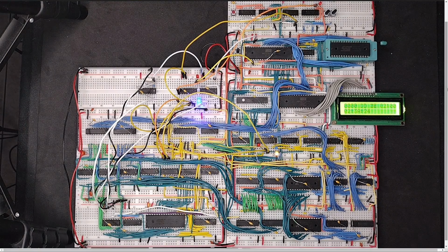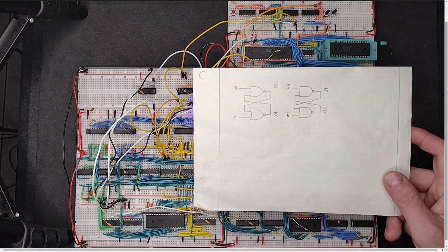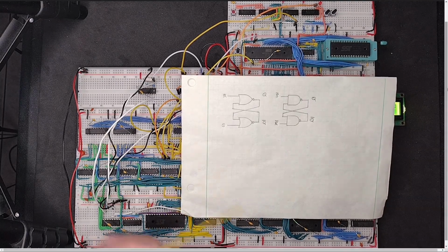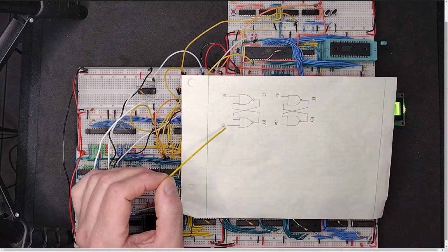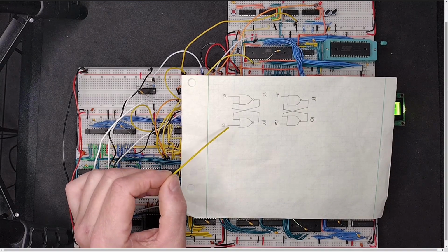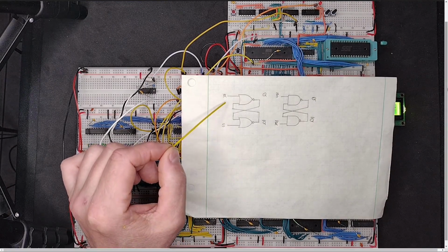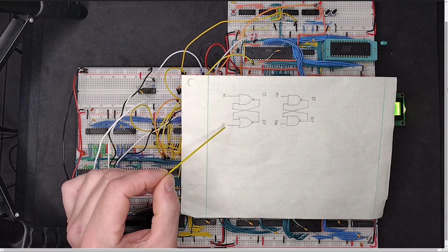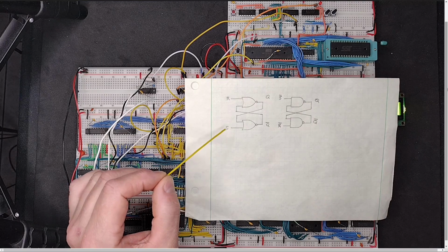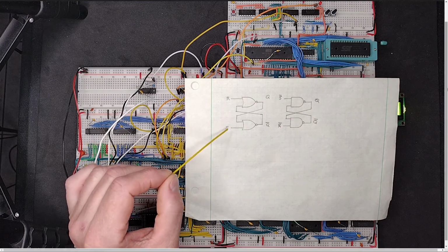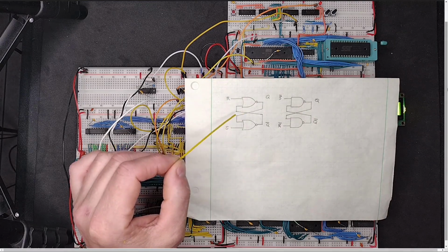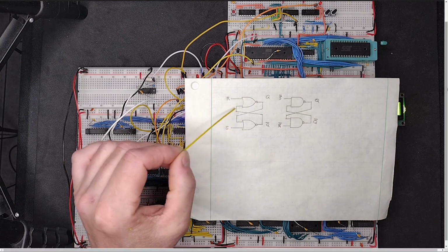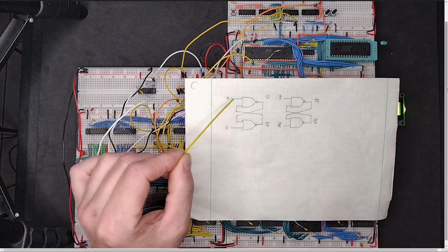So how we're going to do that is to use our old friends, the SR flip-flop. The idea of an SR flip-flop is that you can use one signal to turn the flip-flop into an on state and then a separate signal to turn it to an off state. That's exactly what we're going to want to do here, because we're going to want to have a way for whatever's causing the interrupt to turn on the interrupt. And then we're going to want a way for the computer, with a separate signal, to turn off the interrupt. So an SR flip-flop is perfect for that.